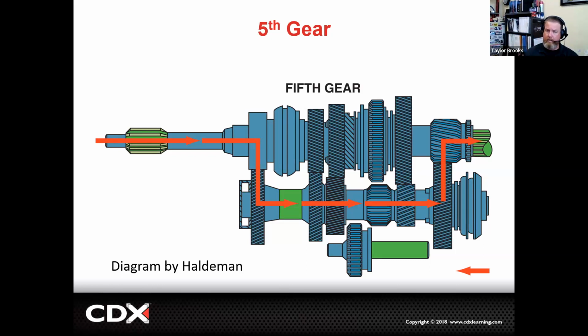Now we'll also notice too on this design that in this particular transmission the fifth gear synchronizer is actually on the counter shaft and not on the output shaft of the transmission, which can be unique in some situations, but isn't unheard of.